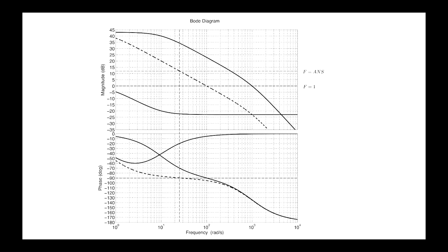If we now look at putting in, in this case, a lag compensator, right? So now we're looking at L being F times C(s), but the lag one, which is denoted by C-minus times A(s), right? Here's A. There's one pole kicking you down, there's the other pole kicking you down, so that here you're going down at minus 40 dB per decade. Here's the lag compensator. That's been fixed in the question, so there's nothing to choose here, but you can choose F.